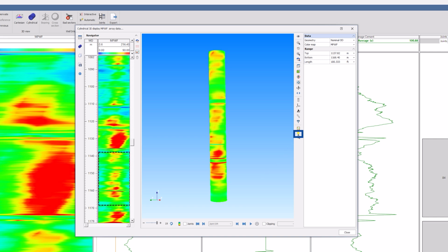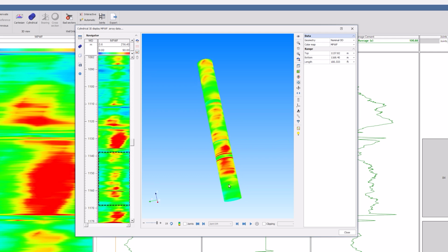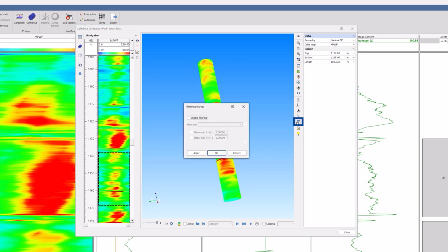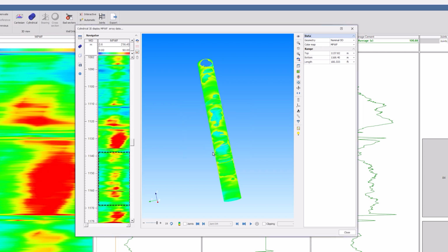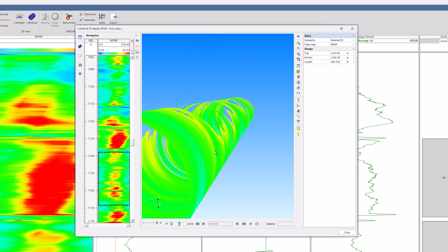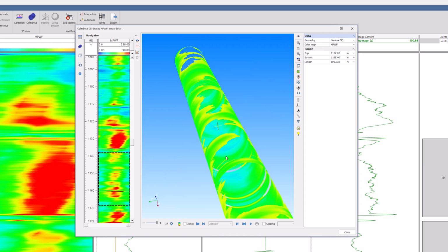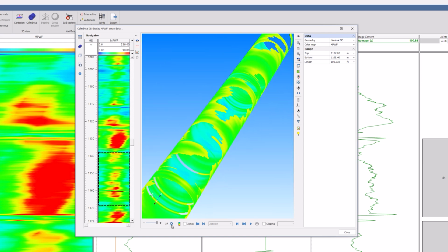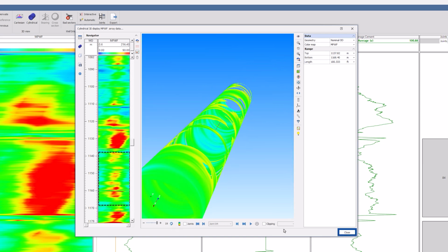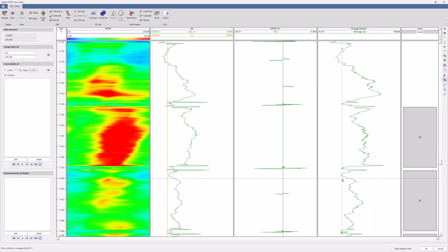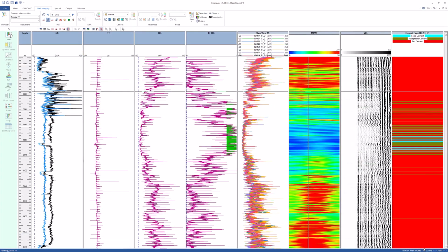High amplitude corresponds to low attenuations, which indicates poor or no cement. The filter option is used to remove the data above a certain amplitude to highlight channels in the annular cement. Leave the Explore with OK.